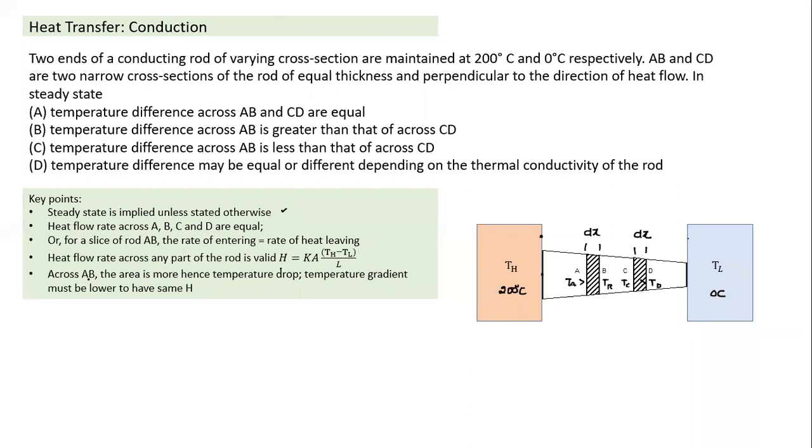When I apply it across AB, the heat flow rate H remains the same: K into the area of AB. I am taking the slice width to be small.